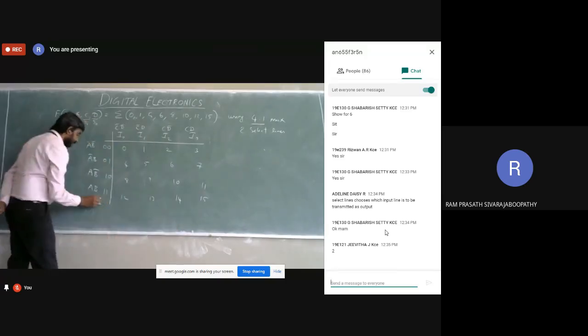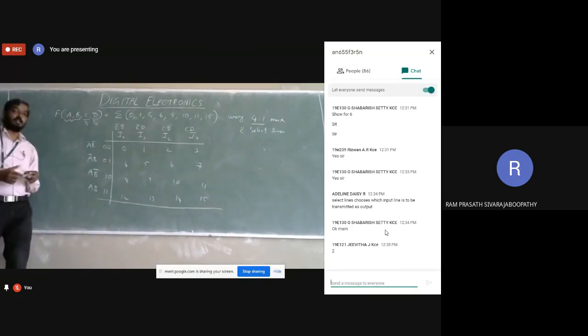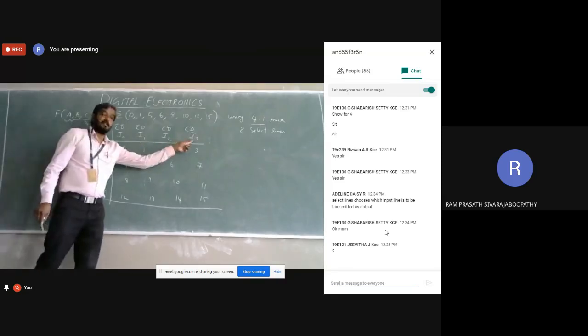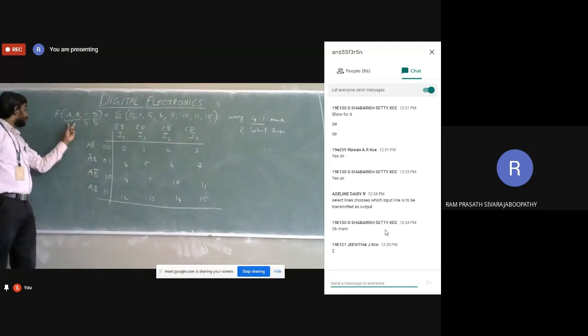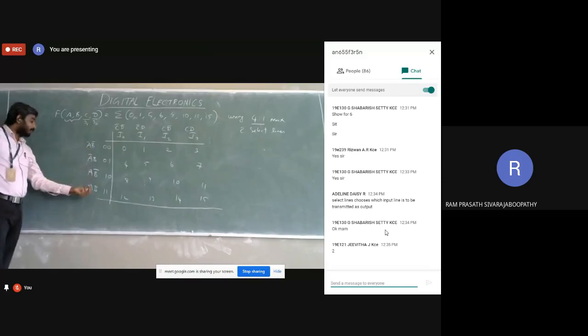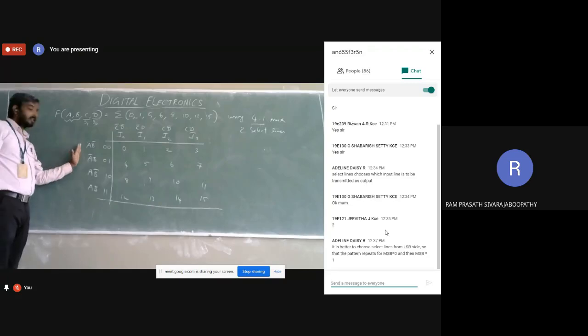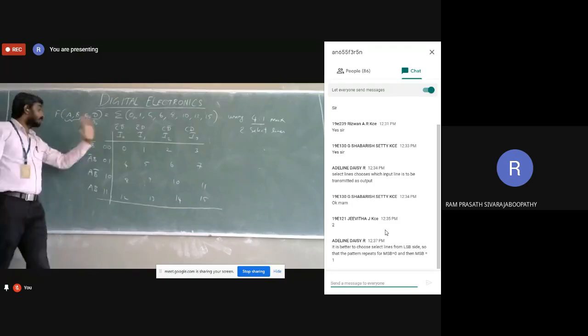Up to this, clear for all of you? How to draw this implementation table: the inputs of the multiplexer, the missing variables A, B, and their 4 combinations 0 0, 0 1, 1 0, 1 1. Please remember, it is not a K-map table; you should not think of 1 1, 1 0 ordering. Normal numbering we are using.